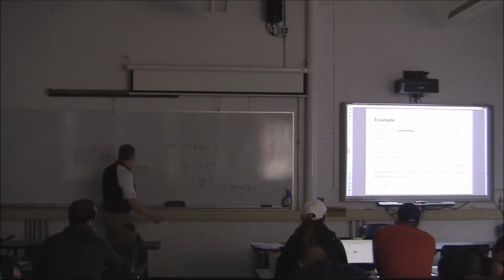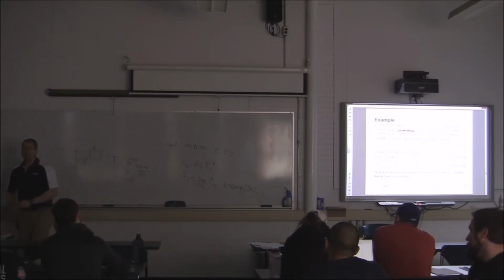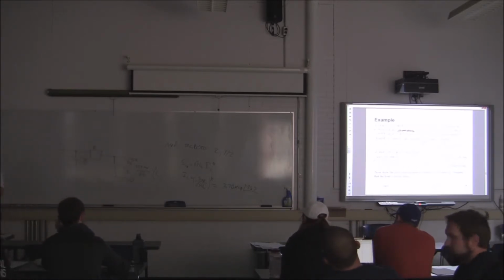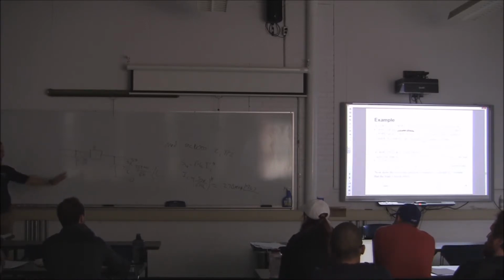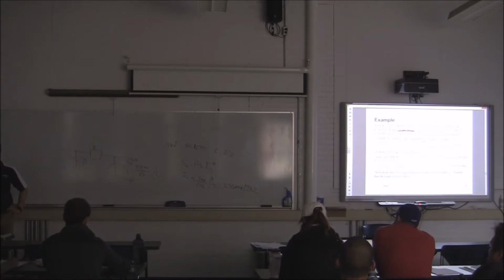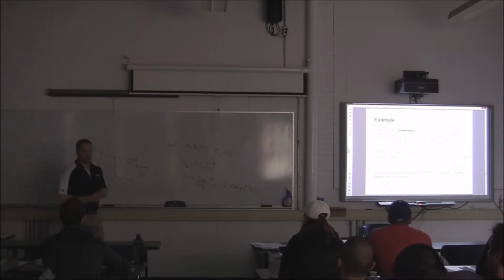So if you notice here too, I also showed I R. It's after the transmission line, right? So it has nothing to do with the transmission circuit. The transmission circuit will change the power factor, but it's on the load, so it hasn't even seen the transmission line yet. You need to calculate that. Does everybody understand why I got a negative 36? I haven't finished solving for it. I've just put S in there. I'm just trying to make sure everybody understands why I get the negative 36.7, but you're right. I do need to add that.